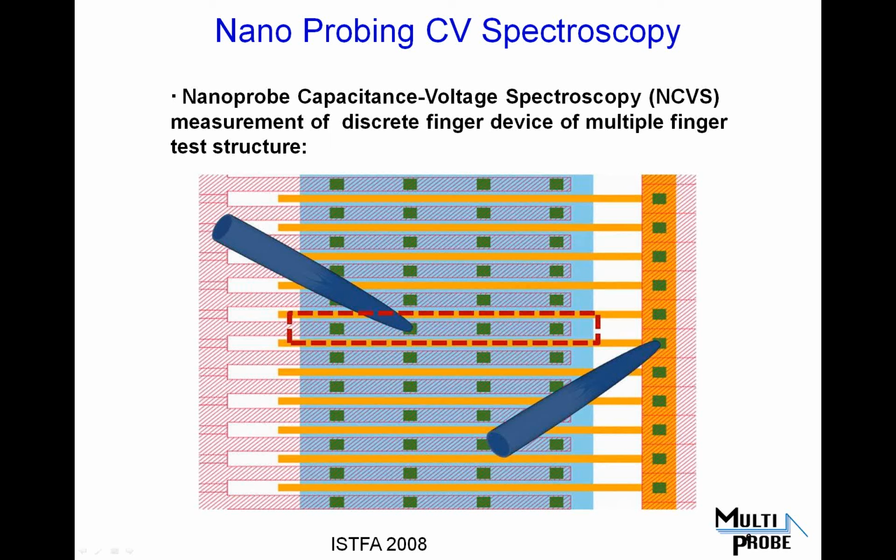Yes. Well, this is effectively the same thing as the source and drain being shorted, because of course the gate separates the source drain regions, but we're making contact to all of the gate fingers and therefore controlling the charge on them, and the only place that we're varying the charge is in the source drain region. So it's really a single pad test structure. You could easily do it with two, of course, and just control the source and drain independently. That's fine, but this one in particular is a 2-probe measurement because the test structure wants that.